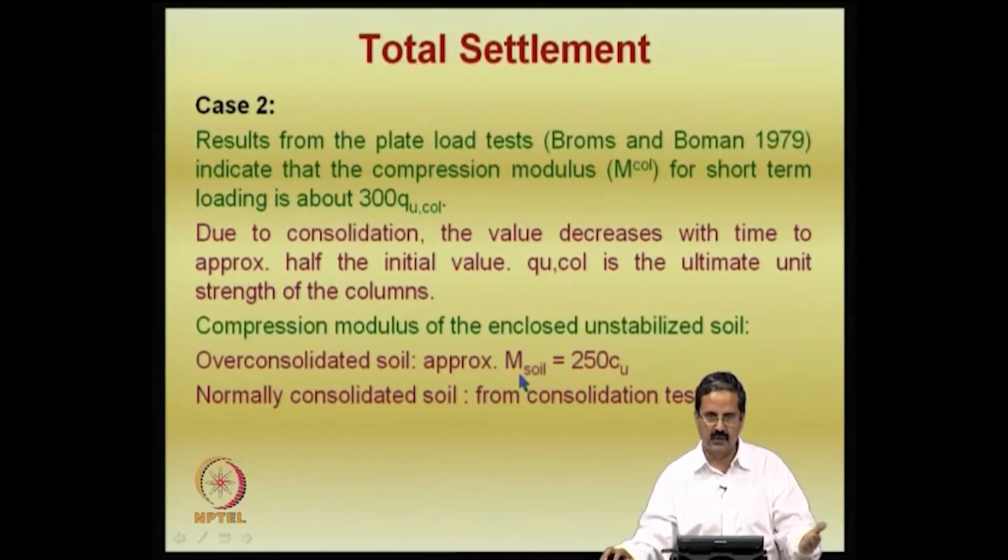Say for example 100 to 200, the 100 kPa is the total stress divided by the strain it has undergone. So, for example, 100 kPa divided by 0.05 gives you some 2000 kPa, which means 2 MPa is the modulus. If you really do a test there, you will get some factor like this.